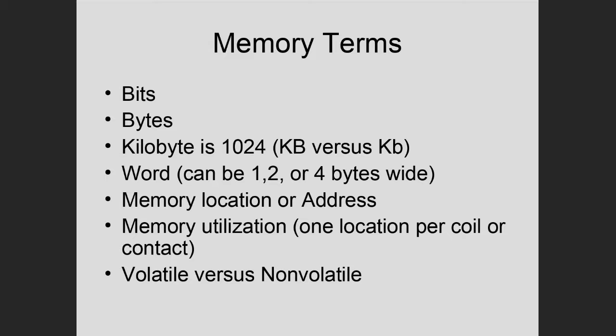Remember that discussion? We talked about data transfer. You can shift bits into a register in single file, serial in, and get them all out at once. That's serial in, parallel out. Or you can shift them in parallel and shift them out in parallel. That's parallel in, parallel out. So there are advantages and disadvantages to all of those I just described.